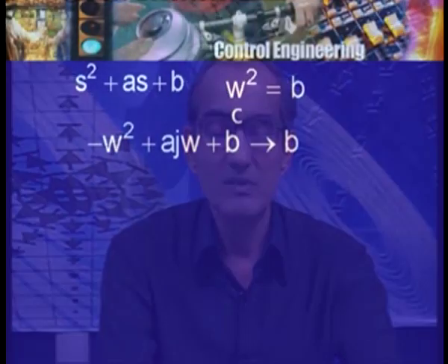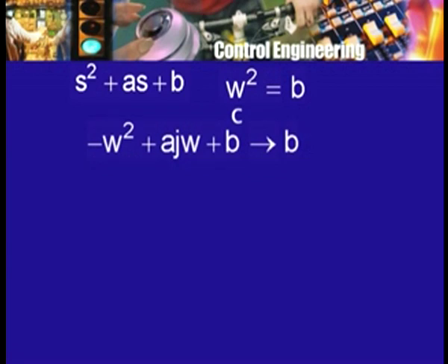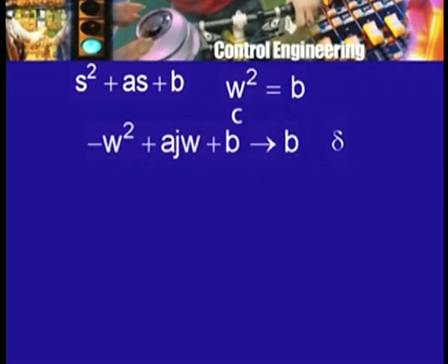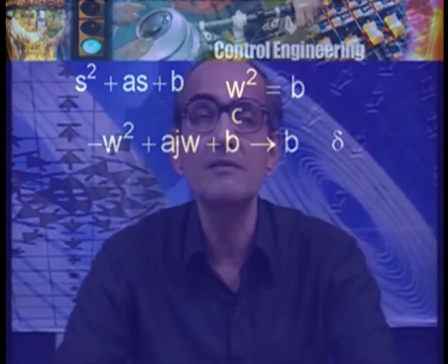Of course, when it is in a pair of poles, this is in the denominator, so the phase shift is minus 90 degrees, and if it is a pair of zeros, it is in the numerator, so the phase shift is plus 90 degrees. Now, once again, in this case, one can make some calculations of phase shift at frequencies which are an octave or a decade below or above the corner frequency, but once again things are going to depend on the damping ratio delta. So, in practice, one could of course make reference to a set of normalized curves which are available in some handbooks.